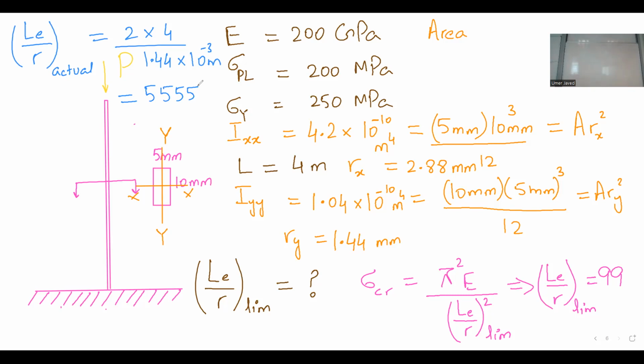Yeah. Using the R value, you're looking at the moment of inertia. For example, if the Ix is much lower than the Iy value, you will use the Rx, right? Ix is less than Iy value. Then Rx is less than Ry. Yeah. So we will use the Rx.